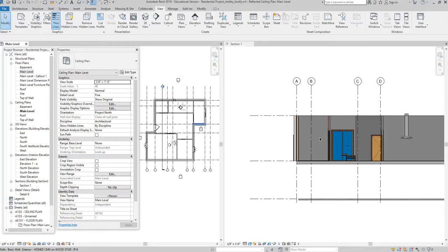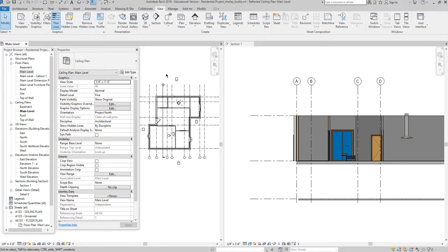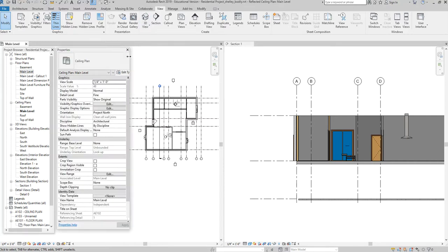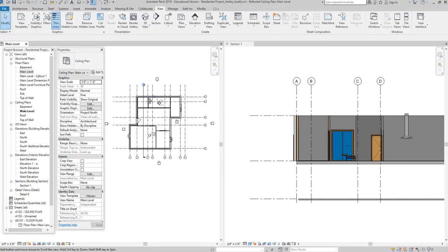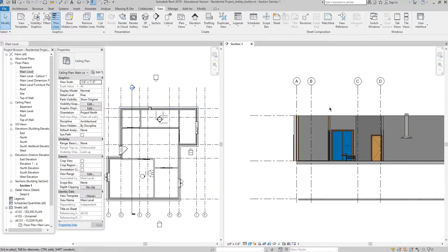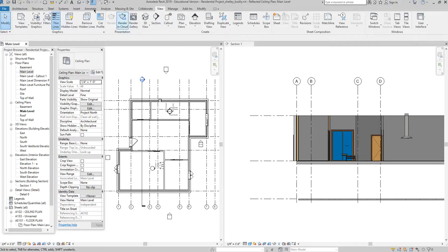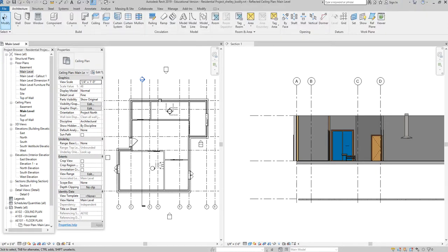These must be 8-foot tall doors. So I'm looking probably somewhere in the range of here upwards, okay? So when I want to create my ceiling, just to see, so we won't all be surprised, right? My ceiling is going to appear somewhere in this range. Ceilings are really easy to generate. I'm going to go to my architecture tab here. You're going to notice that under the build tab we have ceilings, okay?